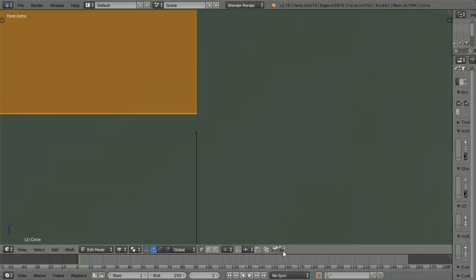Oh, and I have these things joined. I don't know if you can see my mouse button. You can probably see that little X, but right underneath that X, there's these little things. They have 2 arrows and they're touching. And what it says is automatically merge vertices moved into the same location. That can be advantageous for some things, and in other things I don't like it because it'll move your vertices. When it grabs them, it microscopically joins them at the center, and sometimes that actually shifts vertices. So if you take and turn that off, then it shouldn't do that. Because I was drawing on this Starship project, and it was doing that.